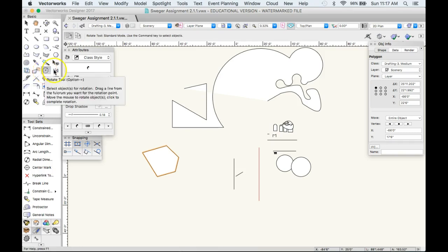The rotate tool always confuses people a little bit. So let's say I have this object right here and I want to rotate it. So I've clicked on the rotate, and also don't forget about your soft keys. Rotate is Alt plus equal. Well, sorry, that's for Windows, not for me. That may sound a little complicated, but I promise you, you'll start to understand it. Like your fingers will just do certain things eventually. You could also get a fancy mouse and set things that you commonly use. And I promise you, rotating is commonly used.